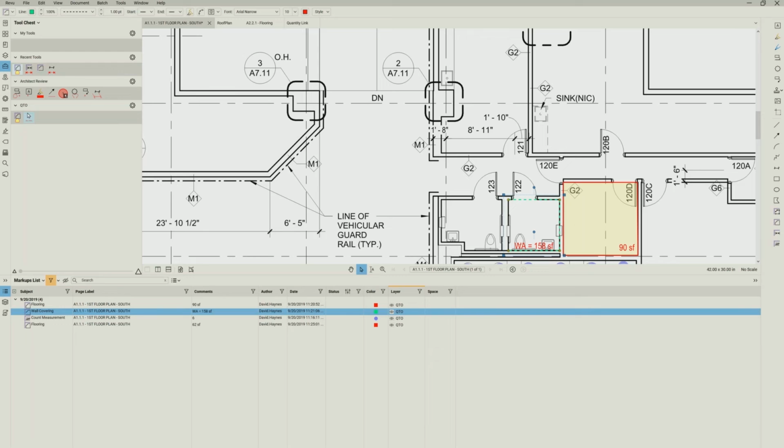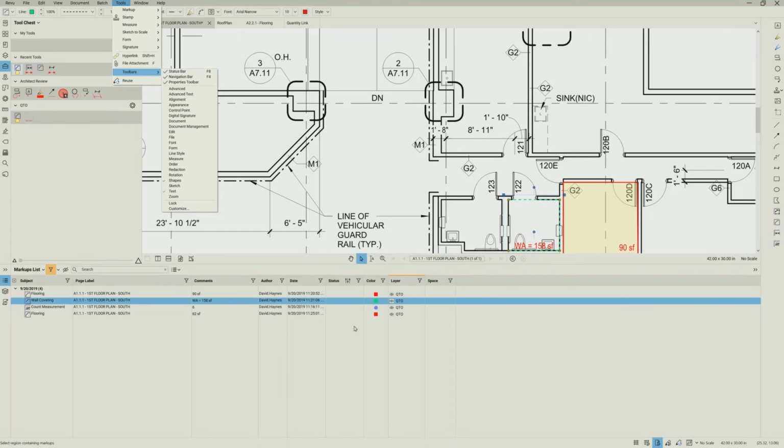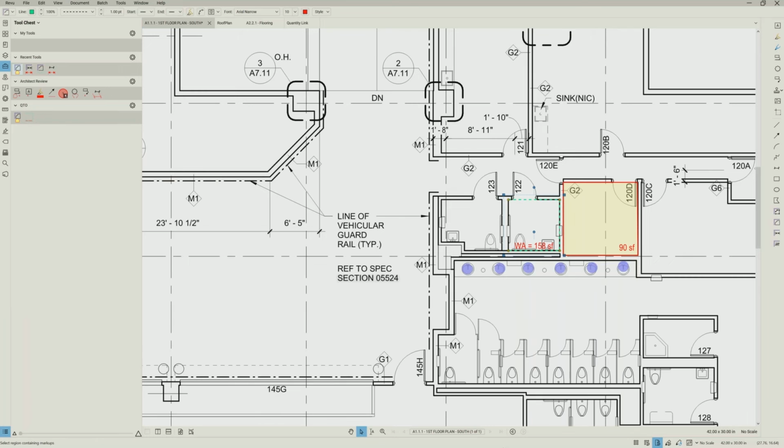First one, I'll make one comment. David showed everybody today how to snap to content by going up to the menus. If you also hit F8 on the keyboard, or go up to Tools and then over to Toolbars, there's a status bar. Let's click on that. And let me move this out of the way. It's down on the very bottom of the screen. There are a few options down there where you can snap to content. So it's an easy one that sometimes, depending on which profile you flip over to, you don't see that toolbar. So that's a good spot to find it. Remember F8 on the keyboard if you don't want to go up to the tools toolbars.